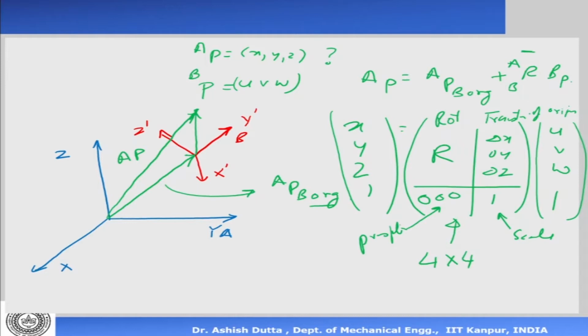Okay, so this matrix relates the coordinates of a point which is expressed in a rotated and translated frame to that of the reference frame. Now, the next thing that we'll need to see is we'll need to move on to the assignment of frames.